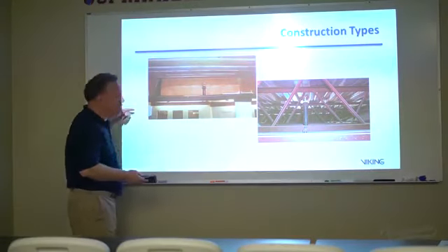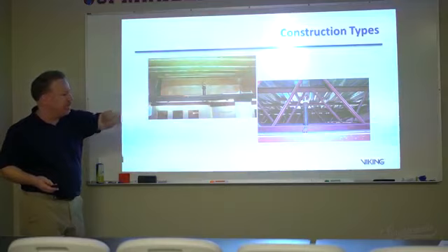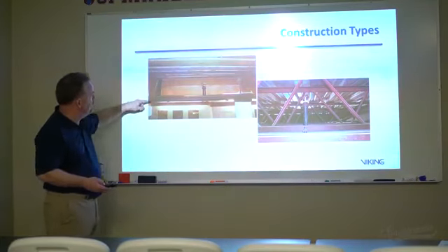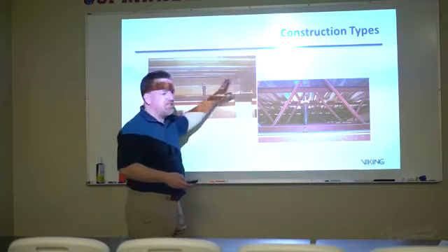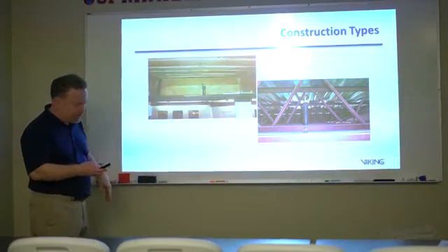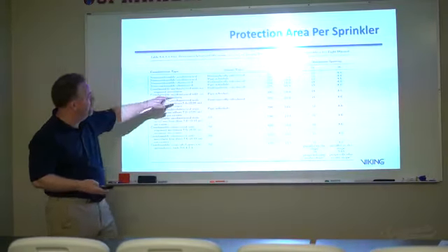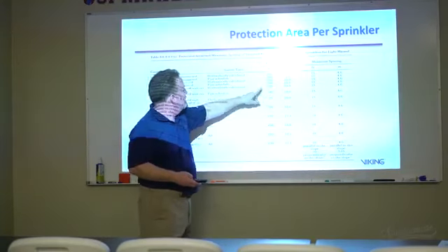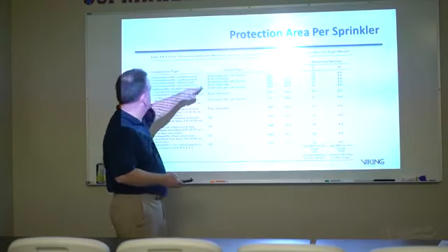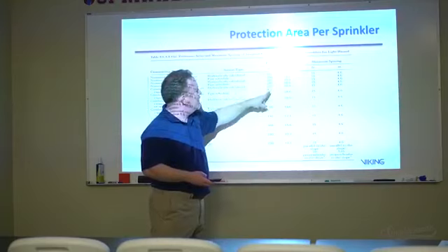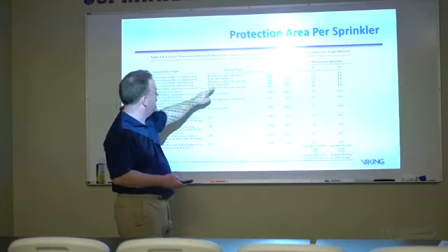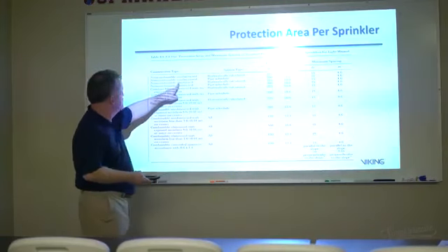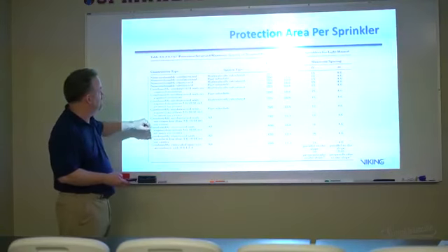Each time, if I get a fire over here, it's got to come over, fill up this, come over, fill up that, which slows things down. So in obstructed construction, you've got non-combustible, unobstructed, 225 per sprinkler; non-combustible, hydraulically calculated, 225, obstructed, it didn't have any impact there at all.